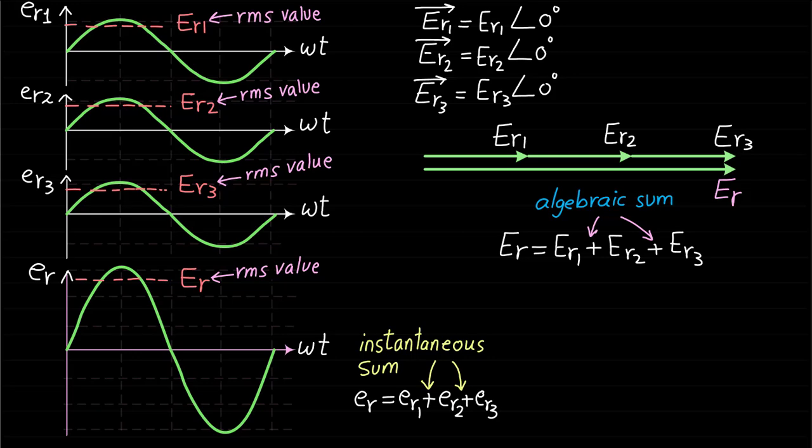Basically, the conclusion was if the phase coils are concentrated coils, then the total RMS back EMF induced voltage ER will equal the algebraic sum of the coils' RMS back EMF voltages and therefore equal to 3E, where ER1 equals ER2 equals ER3 and equals E. Again, the phasor ER is equal to the algebraic sum of the RMS values of the back EMF voltages ER1, ER2, and ER3.